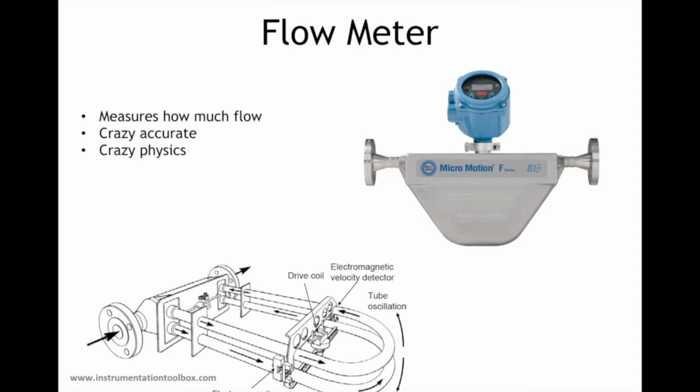There are different types. A very common brand is Micro Motion, and it is a Coriolis flow meter, which is just a really cool concept that people can figure out how to make. There are two coils. There are two loops. These two flow paths are being forced to oscillate, but exactly how much they oscillate is an indication of how much flow is going through there. So these are very sensitive pieces of equipment that give very accurate indications of the flow rate going through there.